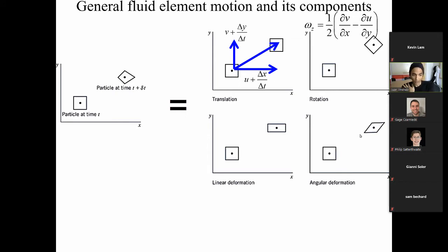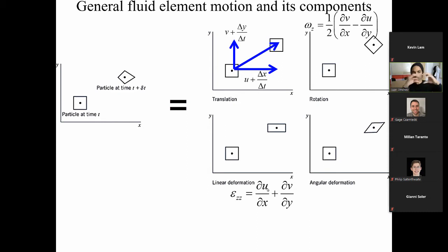All right. So then we also talked about linear deformation, which we can calculate with the following equation right here, where you see the flow is deforming, where it will be lengthening, or if you have angular deformation, which will be like a shear strain. So here you have a normal strain, shear strain, and then up here we have the angular velocity, and that's how you can say whether we have rotational or irrotational flow. And these are very important.